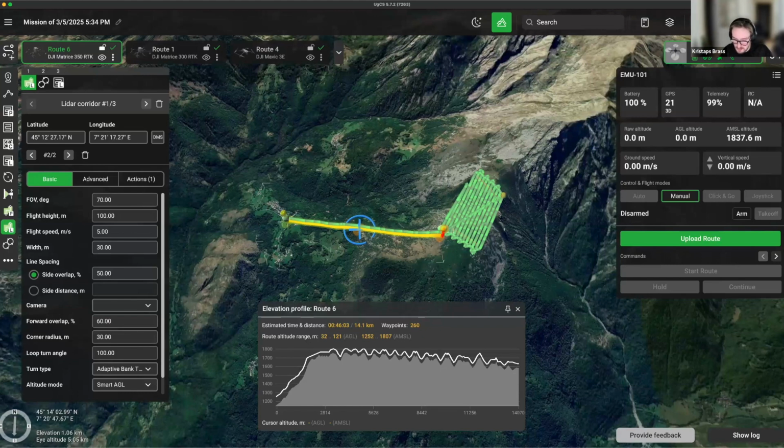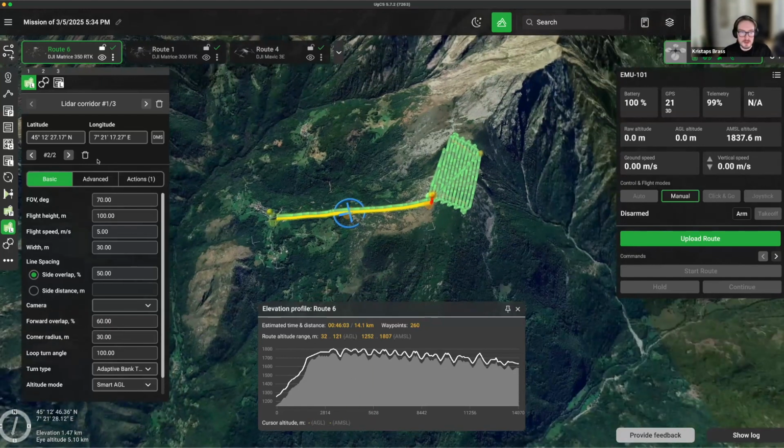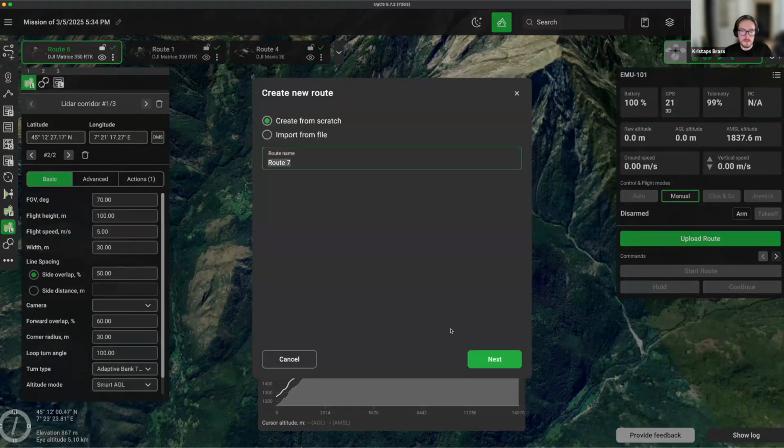Okay, let's now go. There's a question about whether it's possible to use 2 camera profiles with the M350. No, you can't really use 2 camera profiles, because whenever you have all the overlaps and so on, this is set using the main camera profile. So unfortunately, you can't combine 2 of them in the same mission. But let's maybe go into some other flight plans, and then I'll try to answer more of your questions a bit later.